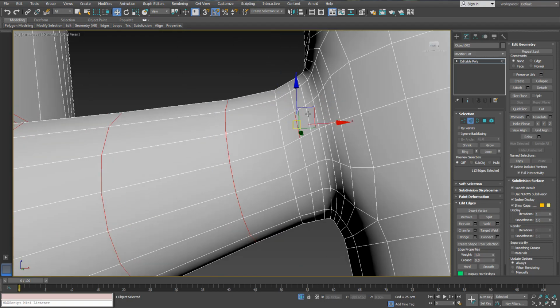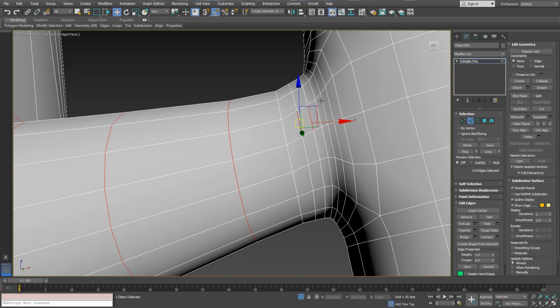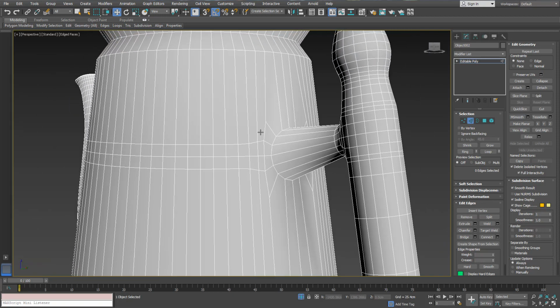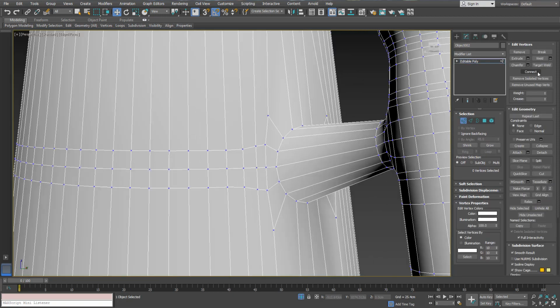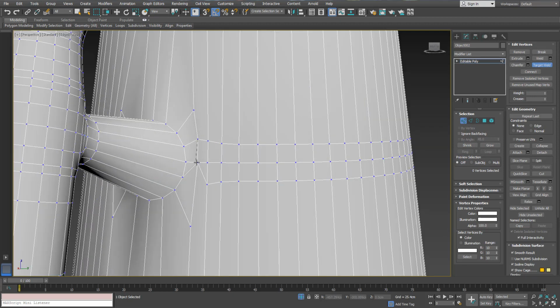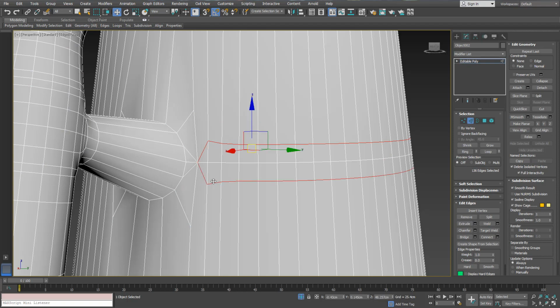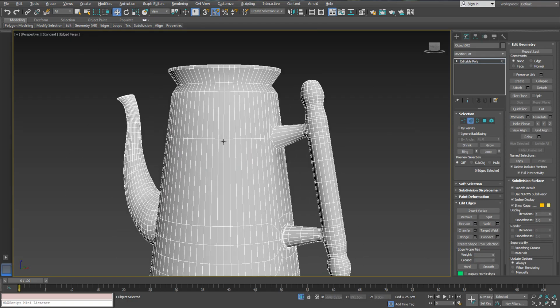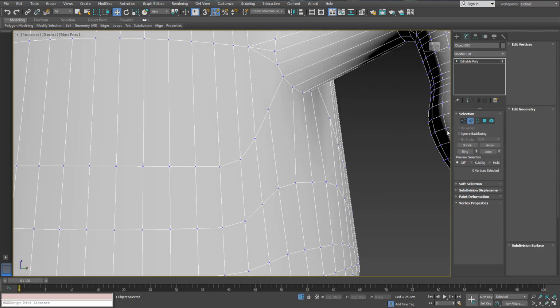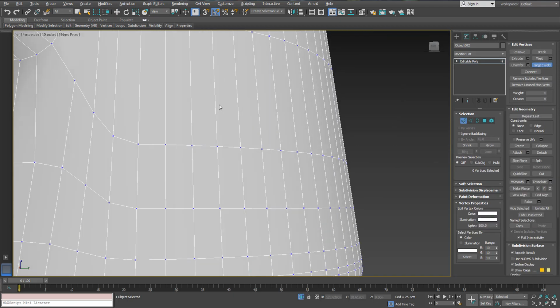And you don't have to follow exactly what I'm going to do. Make sure that you just don't remove the edges that affect the overall silhouette of the model, and anything else is subject to removal. You're going to use Control Backspace a lot in this part.